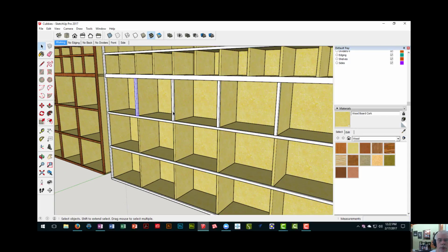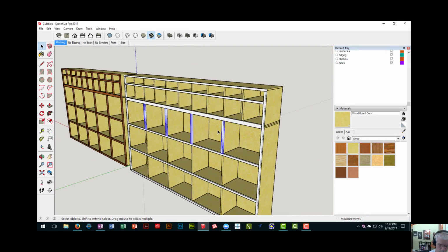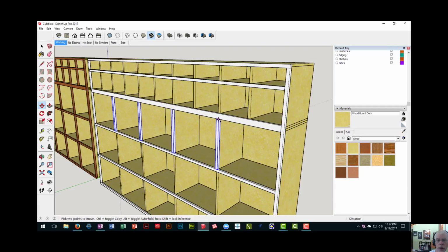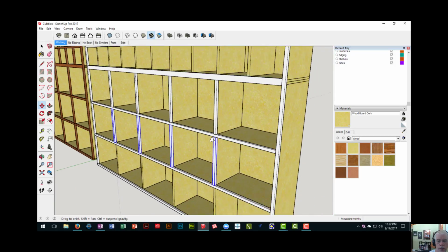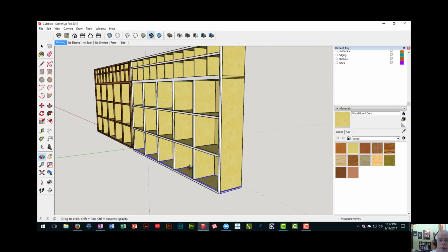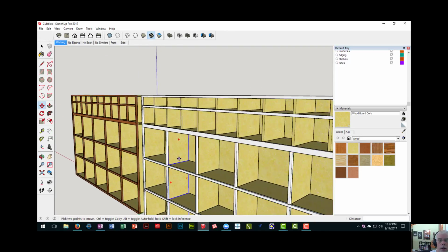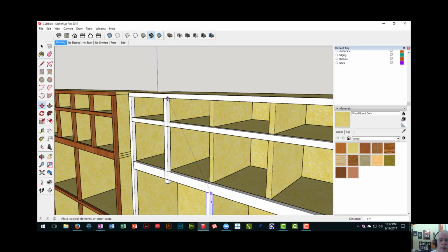Okay. And now I can reproduce all of these guys by shift clicking on them, selecting them one at a time. So I've got 4 of them selected. I'm going to hit the Move key, M, tap Control for copy, and move this right down here and click. And now I want another copy going vertically, so I'm going to do times 2, and that generated the bottom copy. So let's do a similar operation up here. We will copy one of these components even though it's the wrong size, and I'm going to tap my Control key and I'll put it right here.